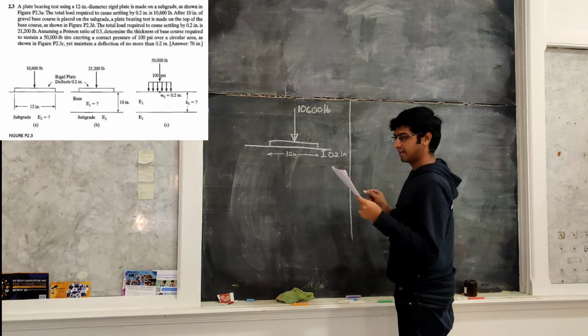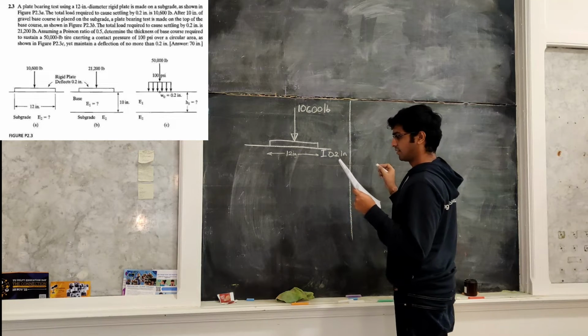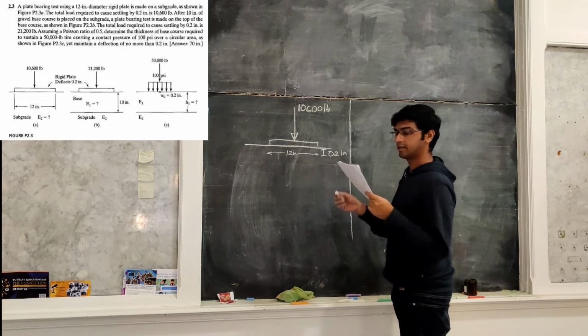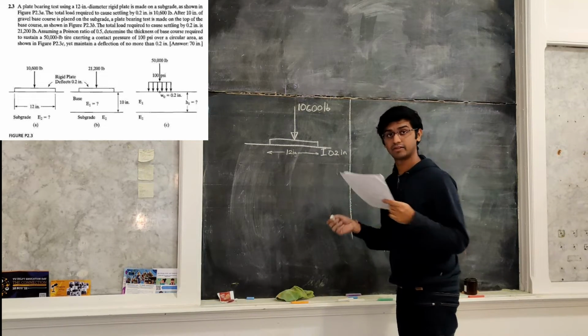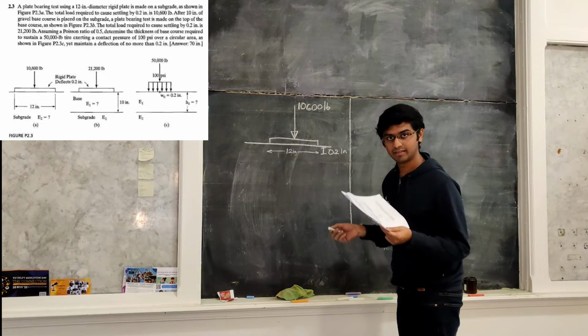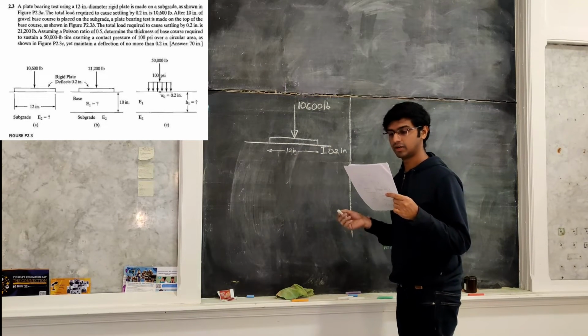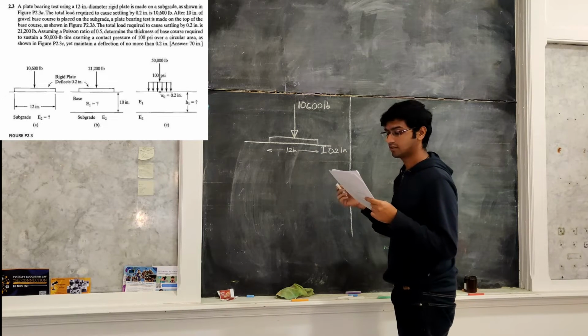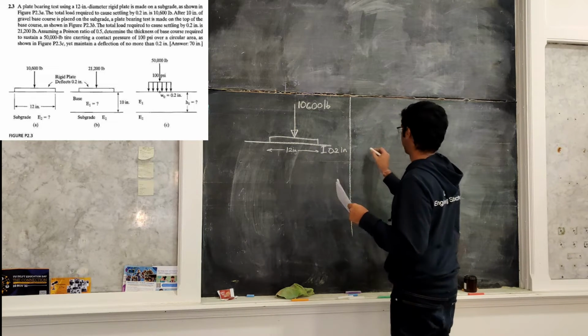In our second case, after a 10-inch gravel base is placed on the subgrade, again the plate bearing test is conducted, for which the load is 21,600 pounds for the same deflection.